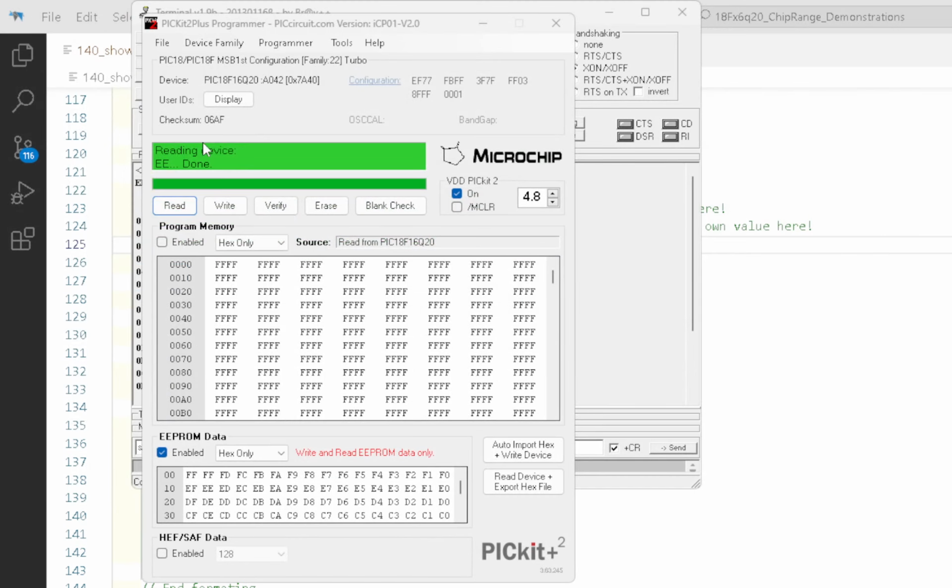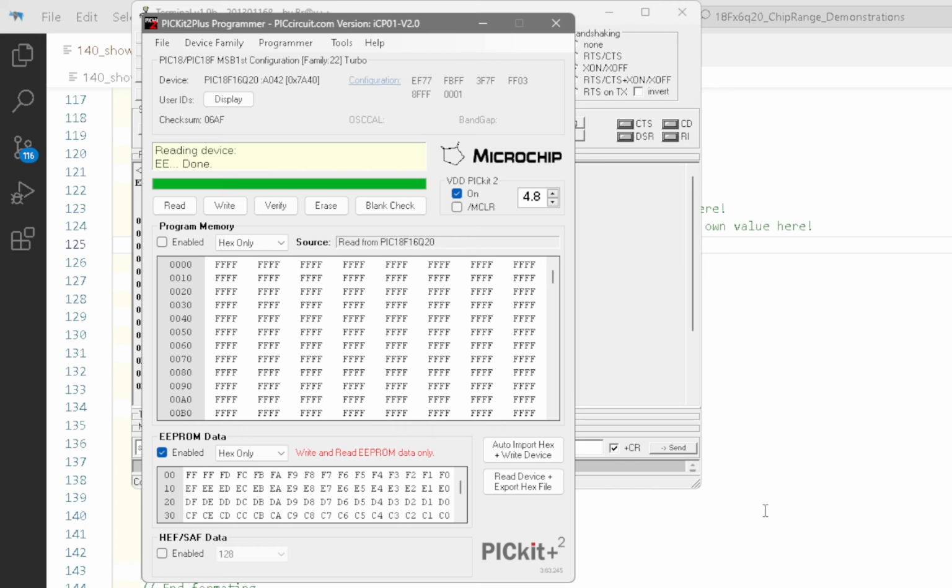And I've got the chip selected already, and I'm just going to select the EEPROM data in this user interface here. I must have one selected, that's correct. I want to have EEPROM selected. I'm just going to read that in. And it says in this bottom dialog box, 255 through to 00, which is what it said.